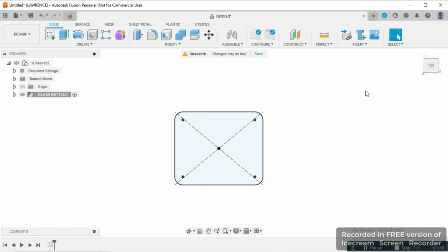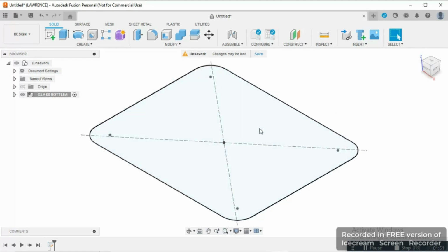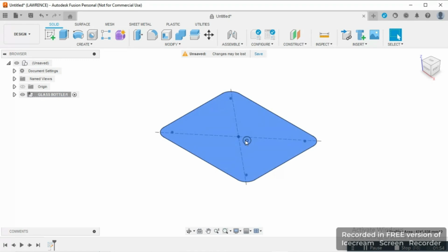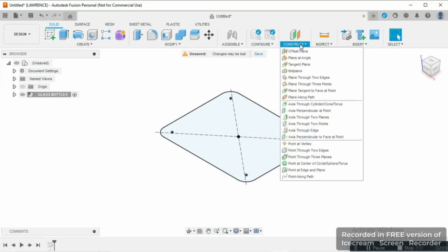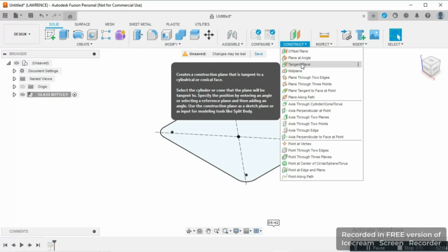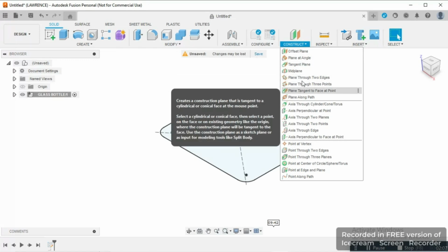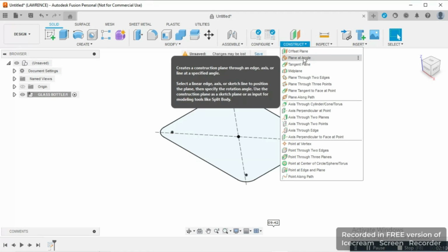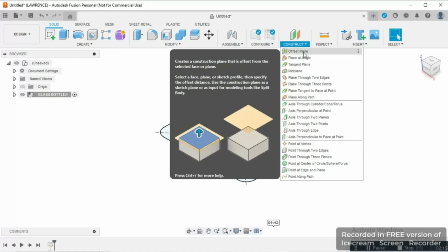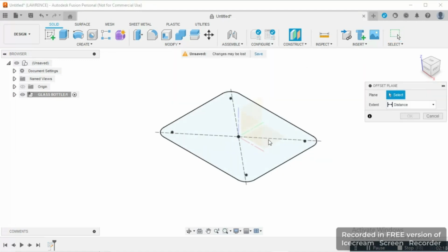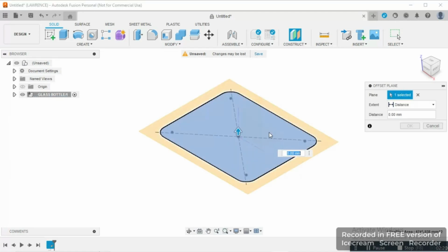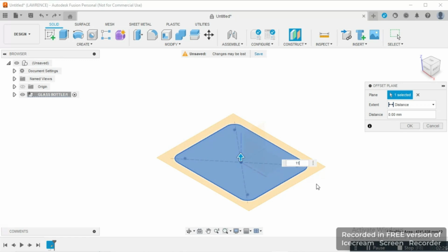Fusion 360 does not allow you to create regular shapes floating in space. All sketches must be started on a planar, flat surface, origin plane or construction plane. We can see the different planes. Offset construction planes are usually used because they always require an existing sketch or a planar surface to offset from. We'll activate offset construction plane and select the bottom origin plane of the previous sketch. We'll specify the distance by typing 114 and pressing the OK button.